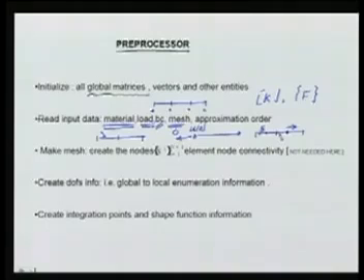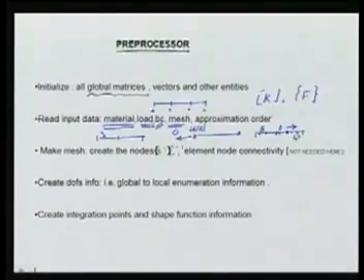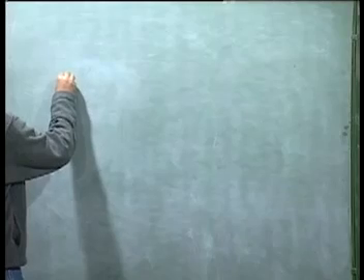In the next subdomain I may want 2, so I will tell 2, it will put 2 elements, and accordingly it will create these nodes which will be stored. In the third one I may have 4 elements, so it will accordingly put the nodes which will divide this piece into 4 elements. Okay, so let us take that example of a domain like this.